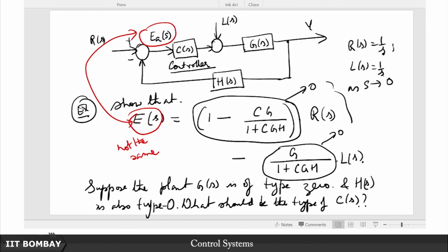What I mean by open is you are excluding the boundary. What is the boundary between left half and right half of the complex plane? It is the imaginary axis. So if you want all our poles in the strict left half of the complex plane, it means we are also excluding the imaginary axis, where, remember, I said that if your poles lie there, the system is marginally stable provided there aren't any repeated poles, but that was with respect to something called BIBO stable.